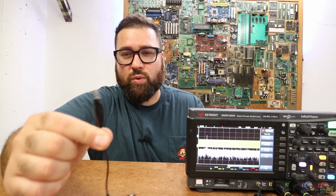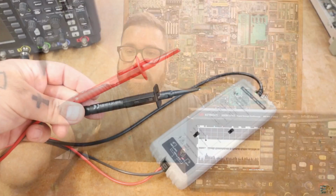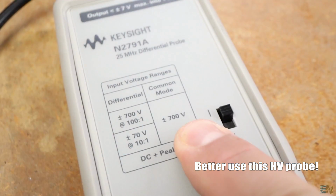You can't connect this ground to any wire that you want to measure, especially for high voltage. If you're measuring something like an Arduino or 5 volts, that doesn't matter. But if you measure something like a mains outlet and you connect this ground to the phase, you basically connect the ground of your home with the phase, and that will be a short circuit.